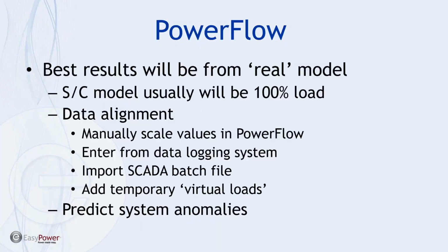what we've generated with a short circuit model is best called an ideal model because what we've used is nameplate data. And as far as the loading, the default setting in EasyPower when you put a load on the one-line diagram is 100%. Now that can vary from time to time, and it makes it difficult, especially when you're designing a system, to know what the load settings will be in real time.